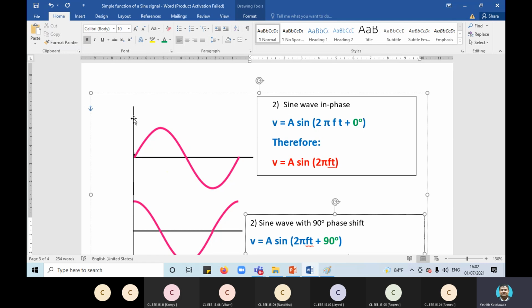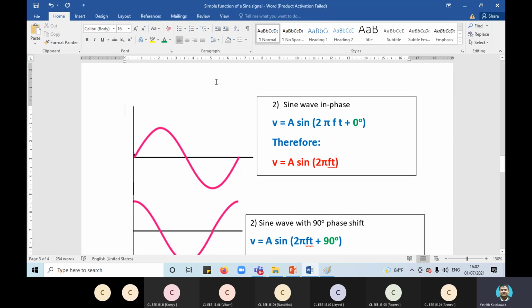Then if you send an alternating current through the base emitter junction, according to that variation you will get an alternating variation on top of that DC component in the collector emitter, so that we can take the amplified outcome. So that is the problem.